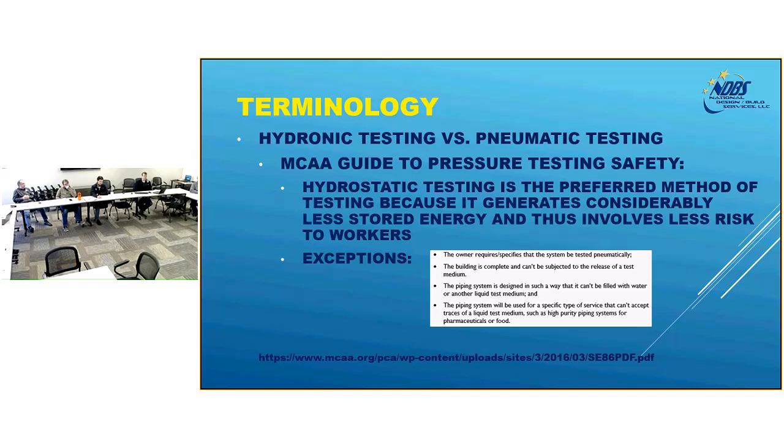If you go to OSHA's website, there are many, many documented cases of loss of life due to pneumatic testing. Gas is compressible, so when you charge up a system with air, it turns that entire system into a giant pipe bomb. We had an incident in IFS not long ago, just this year. Now, hydrostatic testing is better because when the rupture occurs, because water is incompressible, that energy is released localized at that site, and it's dissipated very quickly.